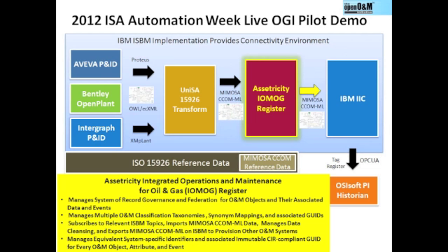This is a standard for operations and maintenance systems, such as our maintenance systems, our tag management systems, our PI historians or historian systems, so they can consume information in a way that makes more sense to them instead of sending them an entire engineering P&ID diagram, which is like, wow, this is really too much. We don't need all that. We need to be able to just get the tag information that we really care about and all the attributes about the tags so we can populate and set up our historians, our operational systems, our DCS, our main systems, et cetera, in the plant. So we've now just got the data we need to be able to provision other systems.